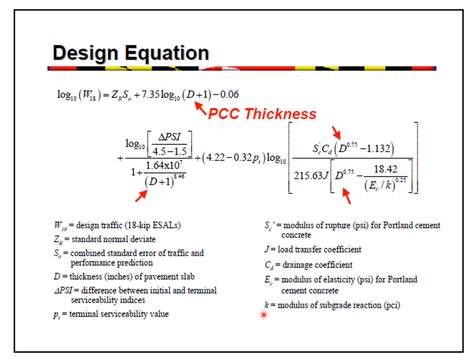Well, keep this thing in mind that the k that is being used over here is the most corrected value of the modulus of subgrade reaction. Certain corrections are to be applied on the modulus of subgrade reaction, and ultimately we will have the corrected modulus of subgrade reaction, and that will be used in the equation.